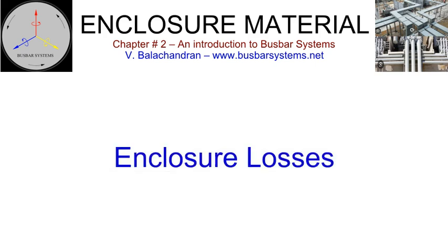Enclosure losses. Any metallic object in the vicinity of a current-carrying conductor will have induced losses. All enclosed busbar systems have metallic enclosures. Non-magnetic metallic enclosure, such as aluminium or stainless steel, will generate eddy current losses. Magnetic metallic enclosure, such as sheet steel, will, in addition to the eddy current losses, generate hysteresis losses. Metallic segregation, if provided between the phases, will also generate losses and are considered as part of the enclosure losses. These losses are sometimes referred to as parasitic losses.